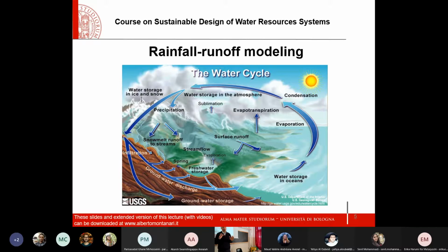Because keep in mind, when you make a small-scale model, you cannot reduce much. You have a limitation on the reduction of scales. So you cannot reproduce a watershed at a scale of 1/100,000 and want to reproduce water circulation in it. It's impossible. And you understand why? Because viscosity becomes too large when you reduce the scale a lot. You cannot reproduce the flow of a river at a scale of 1/1,000 because the water becomes very viscous at a small scale. This is why we cannot go into the lab and make a small-scale experiment for a big river.